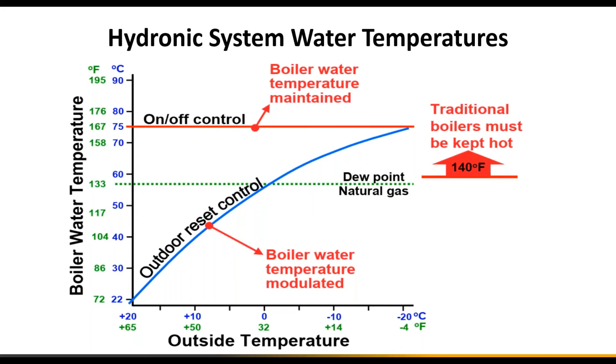With new condensing boilers, outdoor reset has been around for many years. With traditional boilers, the way those are typically operated is at 140 and up to ensure that we're not condensing in the boiler. And then the outdoor reset was typically done through a 3-way or 4-way valve out in the system. With new modern condensing boilers, we can do the outdoor reset directly through the boiler, pick up that additional efficiency gain, and ensure that we're actually resulting in condensation.